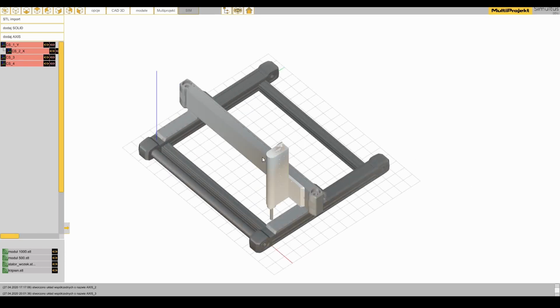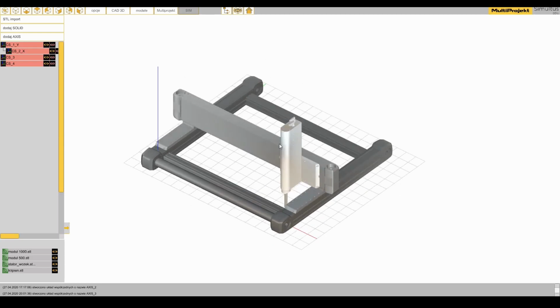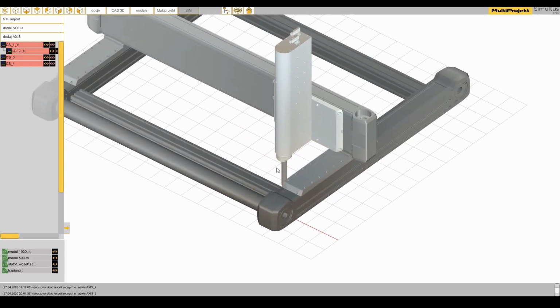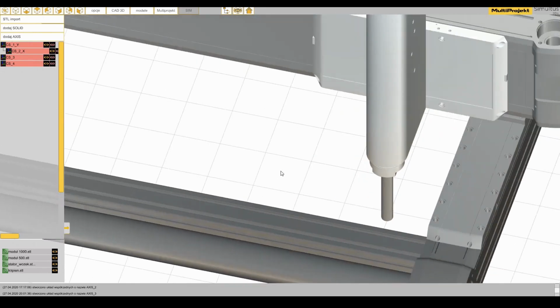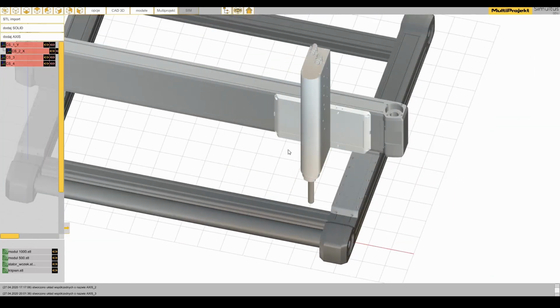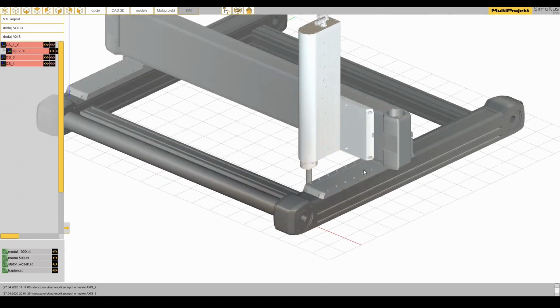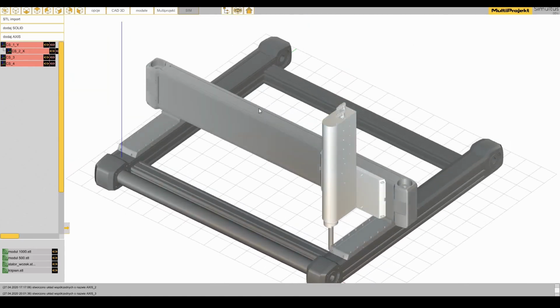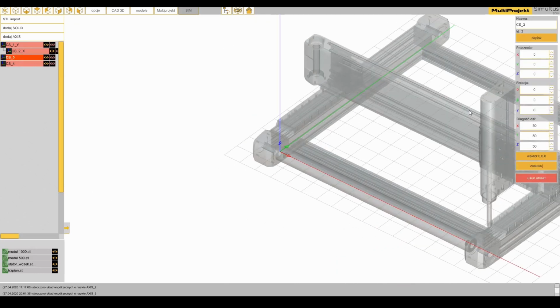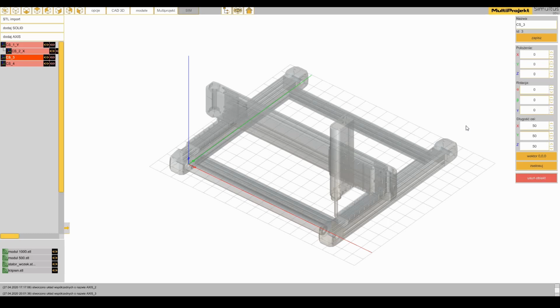Let's move on. Another moving element of our multi-axis module is the Linmot linear rotary motor. The slider of this motor makes a movement consisting of a vertical linear motion and a rotational motion around the z-axis. This combination of these two movements can be performed as a joint motion of two coordinate systems. The first will move vertically, and we will rotate the second. Let's add the letter Z to the name of the third system.